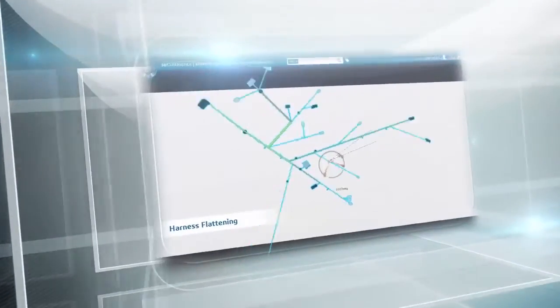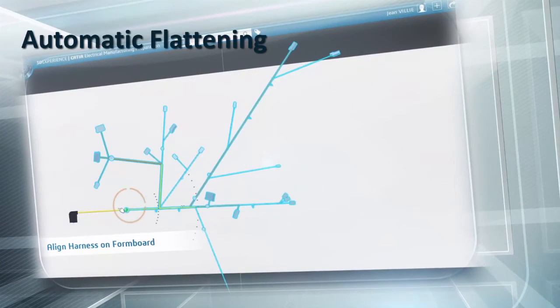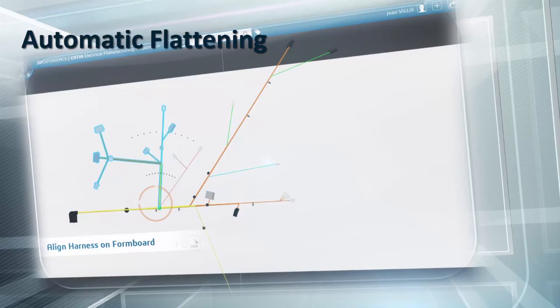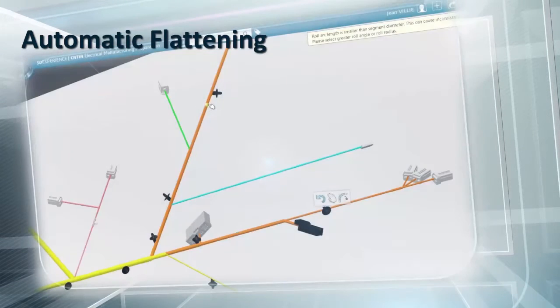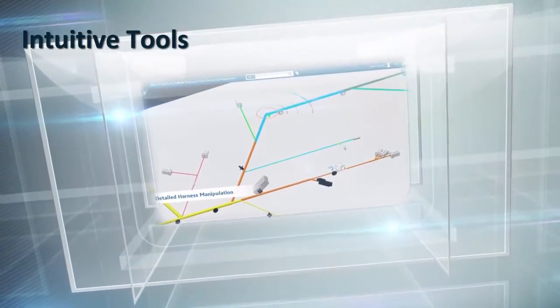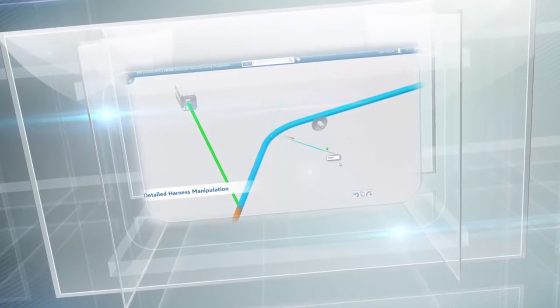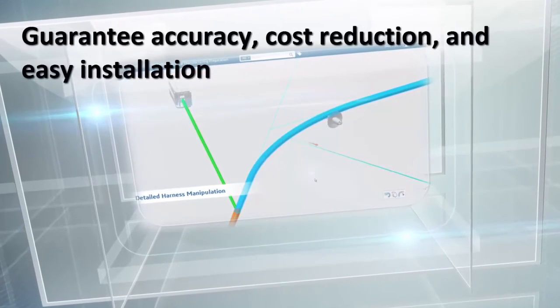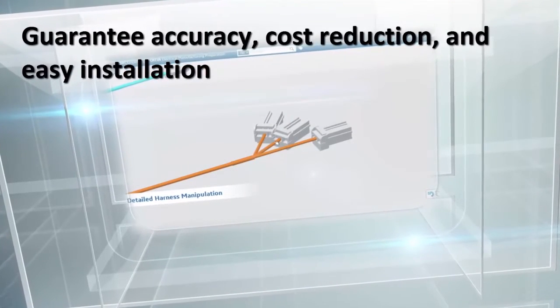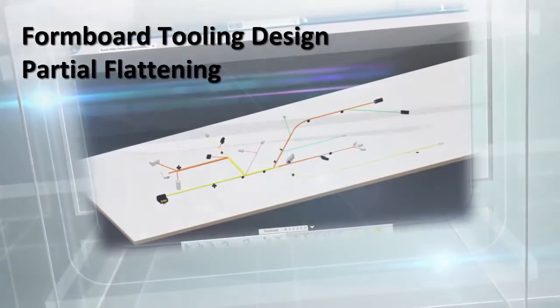Thank you, Dimitri. To summarize some of the key capabilities for Formboard layout design, first, you may have noticed automatic flattening of the 3D electrical harness, a simple click to flatten the entire 3D wire harness. Next, on the 3D Experience platform, we have very intuitive and easy to use 2D harness layout tools to manipulate the bundle segment. The combination of harness design in context plus harness flattening guarantees accuracy, cost reduction, and easy installation of the final product. Some of the additional functionality is Formboard tooling design and partial flattening for complex rigid harnesses.